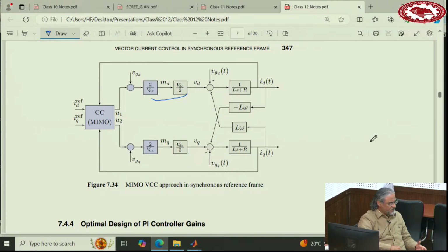Even though in a practical power system we have all the harmonics, only 5, 7, and 11 are really the dominant harmonics. Harmonic 37 is there, but it's very tiny. We don't need to do anything about it. So in the worst case scenario, if you have a few of these resonant controllers, you will be able to handle the harmonics. But is there a way of combining these resonant controllers and doing the job with just one controller? That's also a good question that you can think about.